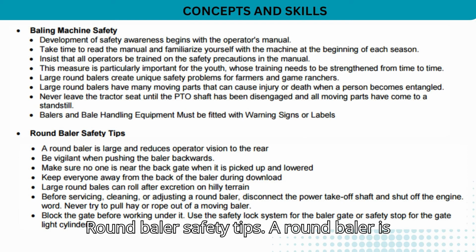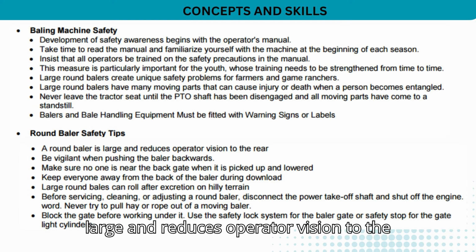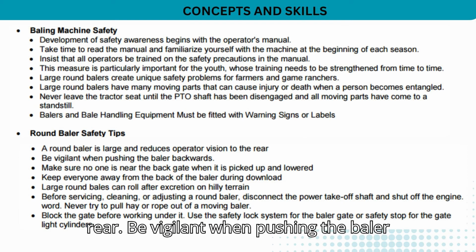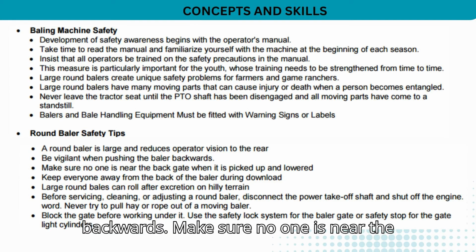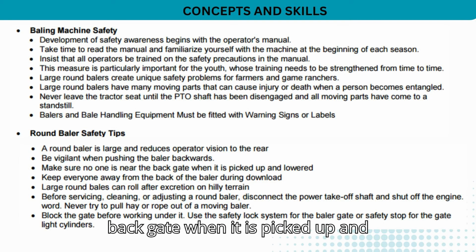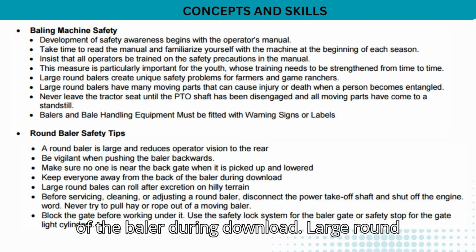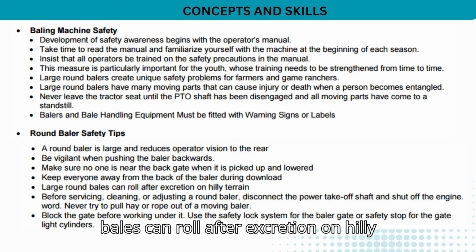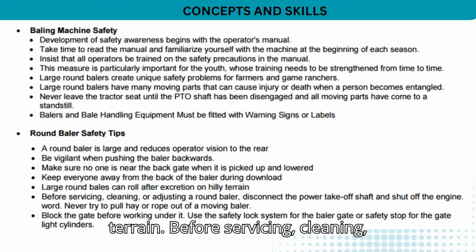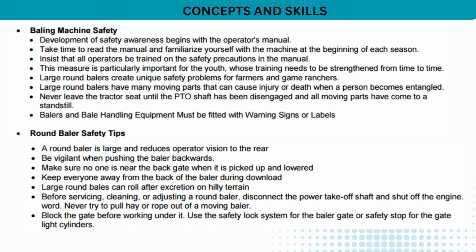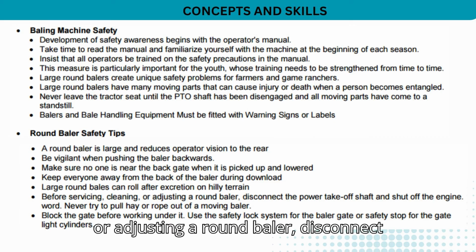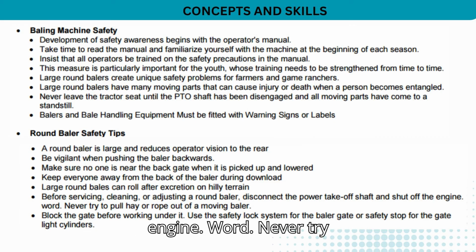Round baler safety tips. A round baler is large and reduces operator vision to the rear. Be vigilant when pushing the baler backwards. Make sure no one is near the back gate when it is picked up and lowered. Keep everyone away from the back of the baler during download. Large round bales can roll after ejection on hilly terrain. Before servicing, cleaning, or adjusting a round baler, disconnect the power takeoff shaft and shut off the engine.